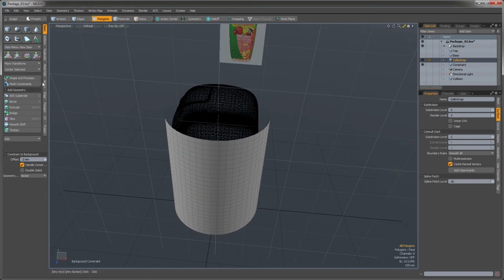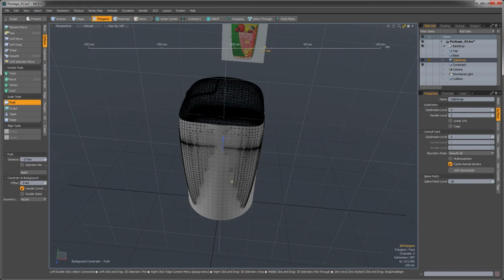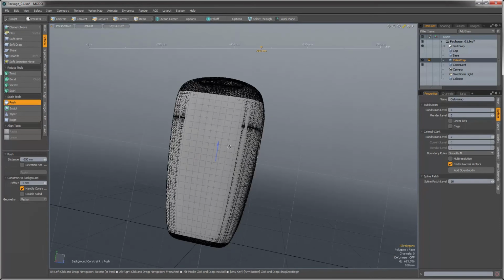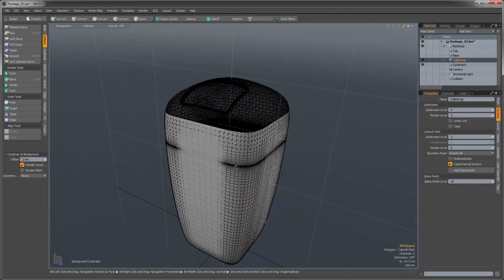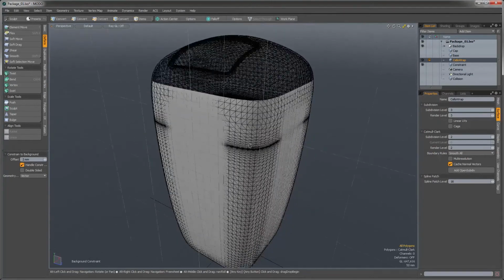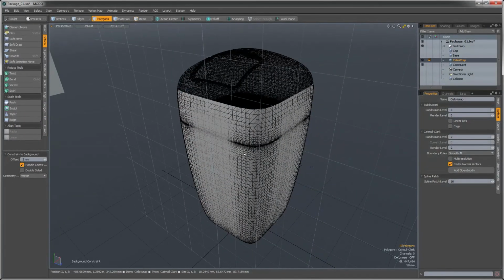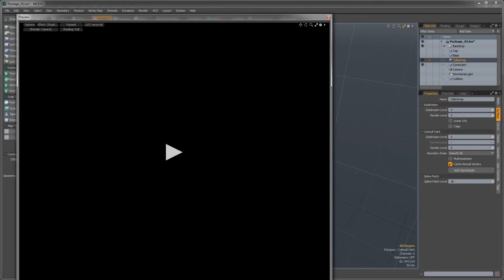So with all those polygons selected, we're going to go to deform now, and we're going to go push. And we want to push that right against that background element. So that was a negative 350 millimeters to get that on there. And then we want to make sure that that is a subdivision surface object. So you can see we're kind of penetrating a little bit on here, but sometimes the 3D viewport can be a little bit deceiving. So I want to open up a preview on this, drag this in from my other monitor,